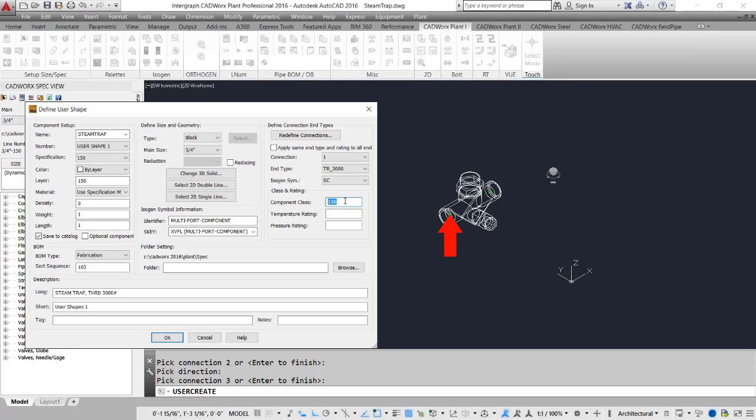This means if we are building, say, a highly geometrically accurate pop-off valve or a pressure relief valve, then you can do that with the proper flanged end types and flange rating for the pressure and relief side for that valve, and you will get the same end type checking for that.